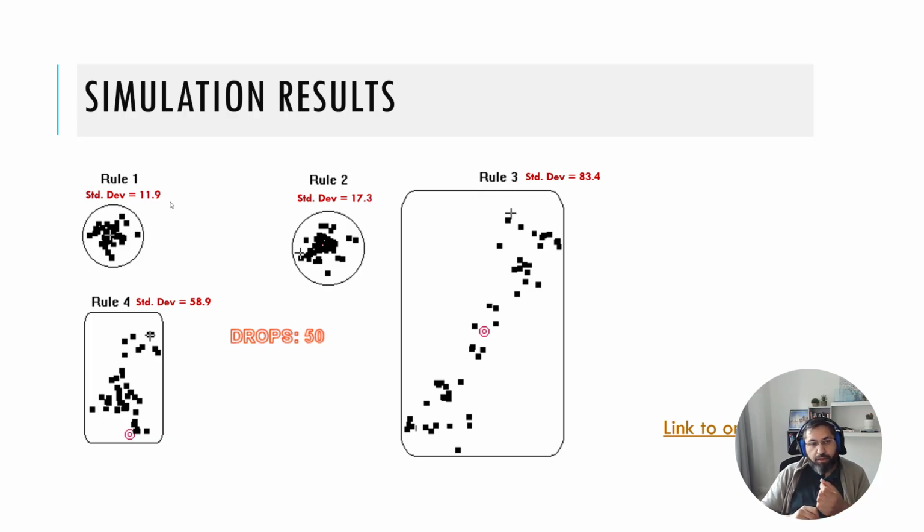Maybe if the funnel was really wide, the operator could drop it right in the center of the funnel so it doesn't touch any of the sides and just drops down vertically. But the funnel is not that much wider than the marble, so that's very hard to do. It's not feasible that the operator can do that every time. So it's going to bounce around the funnel. So it's not operator error really. It's the system, a feature of the way the machine is designed, where the machine is going to have that much error.